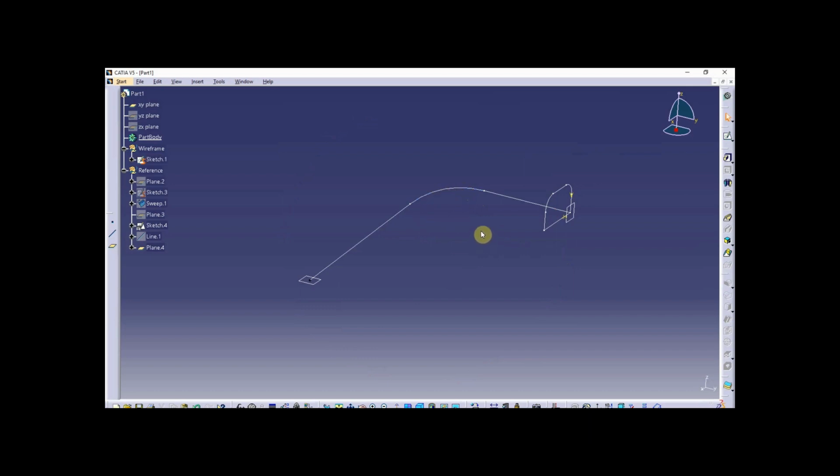Again, it's a sweep. So just a basic definition of a sweep. It's a profile that is swept or extruded along a trajectory. In this case, it's a profile that is swept along a center curve in CATIA. And there are three profile control options. You have keep angle, you have pulling direction, and you have with reference surface, and I'm going to demonstrate all three of those. So let me show you what I have on the screen here.